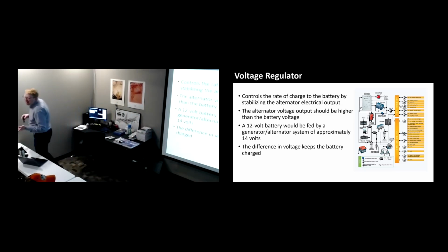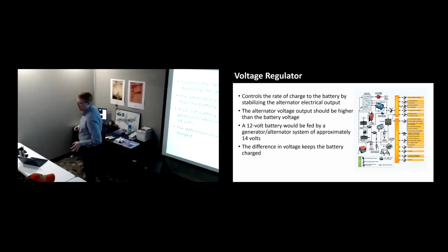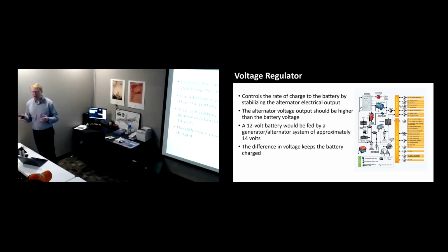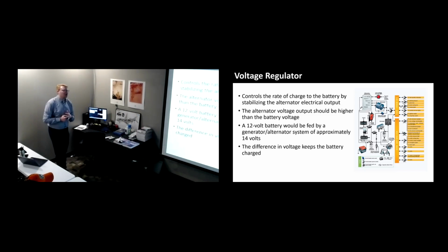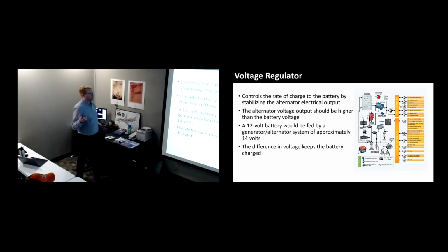If the voltage regulator stopped working, it would start providing erroneous voltages to different systems that don't use that. So if your particular item, say, uses 14 volts and you provide it 6, it won't work. You'll see the buttons on the screen will stop working and the screen will go away. If you provide a really high voltage, you'll start seeing erroneous movements, erroneous things that shouldn't be right. It's rated to a certain power setting. And the voltage regulator is what regulates the whole system to ensure it's working correctly. Cool? You might even see smoke.